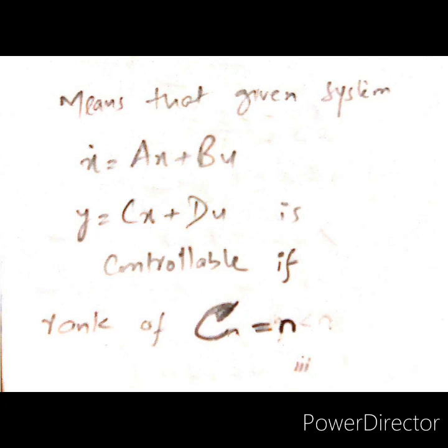And if it is not controllable, this means that we can't use the pole placement method, and we can't take these values of the state vectors in such a way that we are able to achieve the target. That is, we won't be able to get those closed loop poles. We won't be able to get the output to 0. That is only possible when the system is controllable.